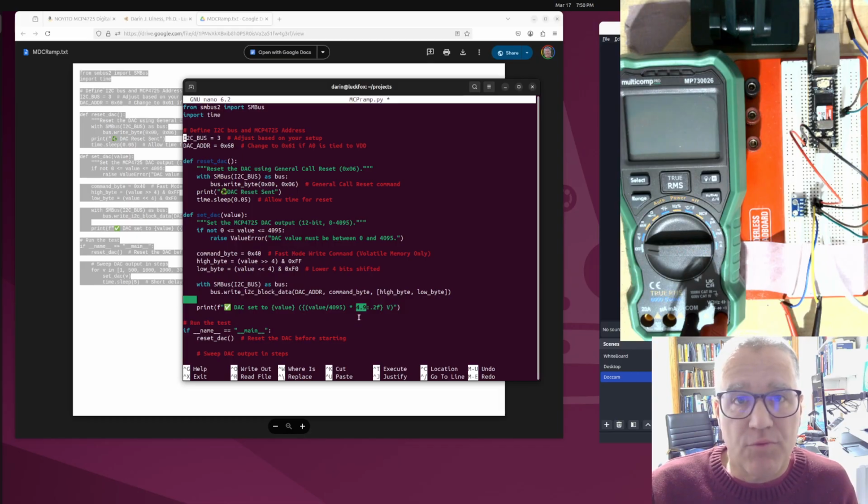So I'm reading 4.9 volts, not quite 5. So I'm changing this to 4.9 volts. And what we'll see, if you get this right, this chip is pretty well calibrated. So it'll be pretty darn close to what we expect for the value once we get to the other program where we're setting a target value.